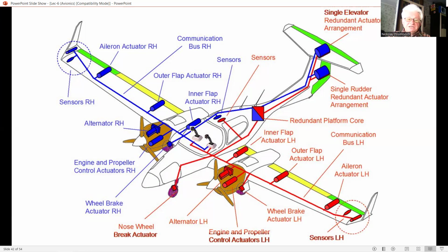Failures can be divided into the following categories. First, hard-over failures, whereby the failed sensor output is hard over to full scale and would demand full authority control surface movement with catastrophic results. Second, zero output failures, whereby the sensor output is zero and thus no control action would take place.